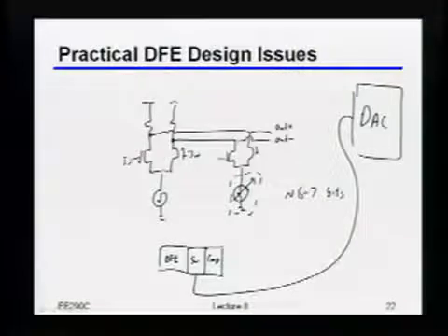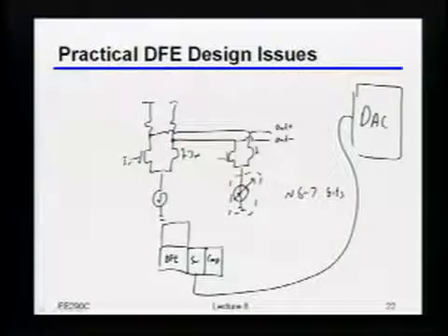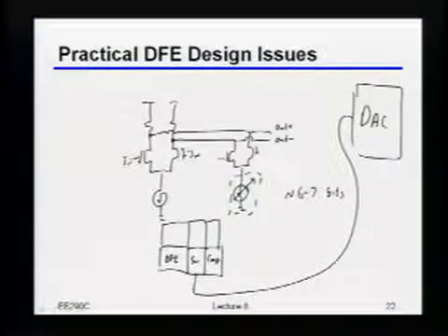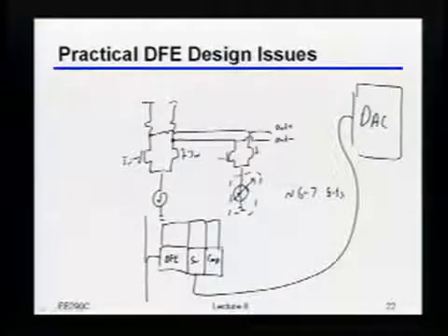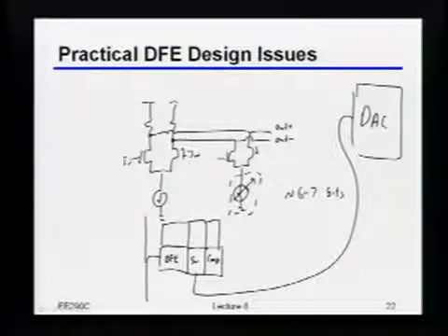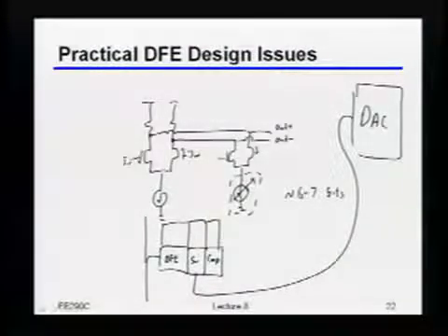Fundamentally the DAC doesn't have to be off on the side. But imagine I have another DFE nearby that I want to do. If I shove the DAC right next to the DFE itself, it'll eat into your pitch. It'll force everything to be spread apart, and then you'll be paying for really big wires in the front. So even though it looks funny, where one circuit is physically spread across like 3 different places, there's usually a pretty good reason to do something like this.